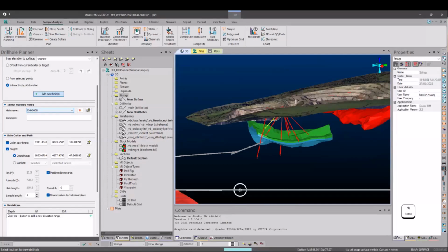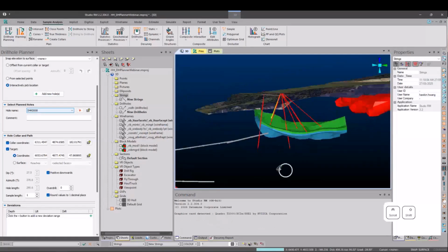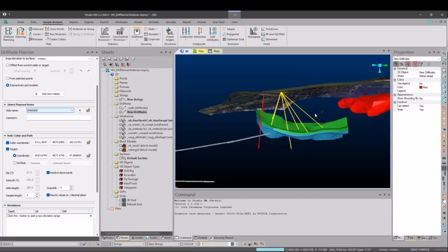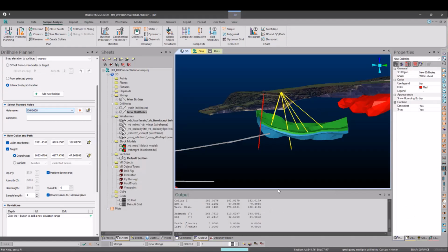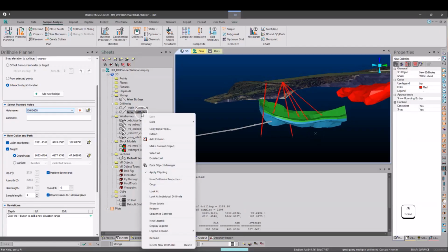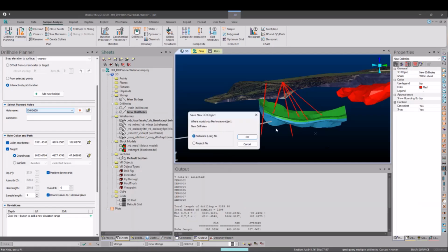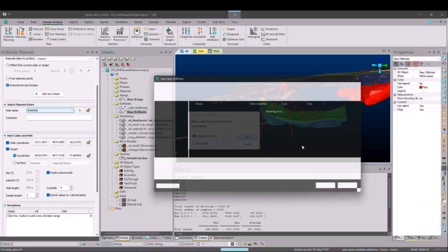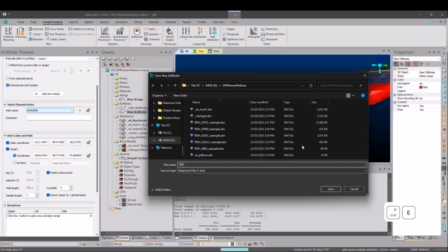Similar to a standard string digitization technique, you can query the total drill hole length or the number of drill holes in the 3D scene. The quick key for that is QMD, or query multiple holes. It will spit out your output down the bottom here somewhere. The total length is 2000 meters. That's a pretty standard resource development or exploration program, and I do have 7 holes. So that's scenario number 1. We can save that drill hole as, let's call it Viking Bounty Exploration.